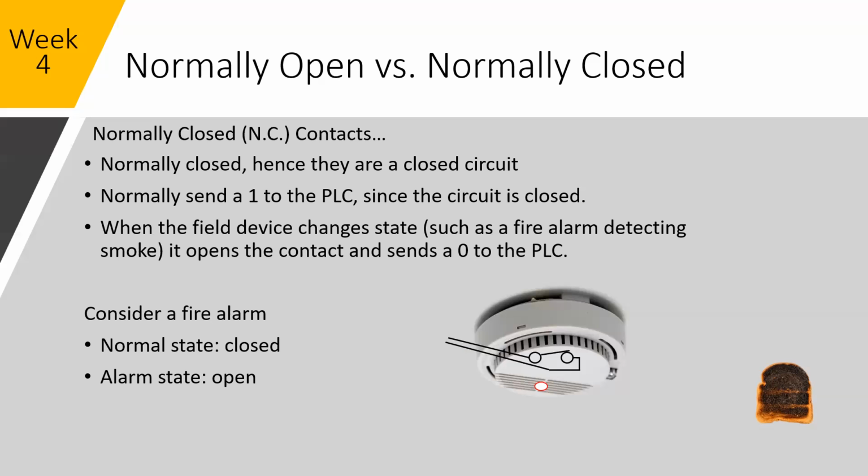Okay, perfect. So depending on the actual hardware for the pendant, the dead man pendant, it might actually be a normally open contact that you're holding shut. And if you were to release it, it would open up again. So there's different applications, and depending on how they're being used, is how it'll be wired.